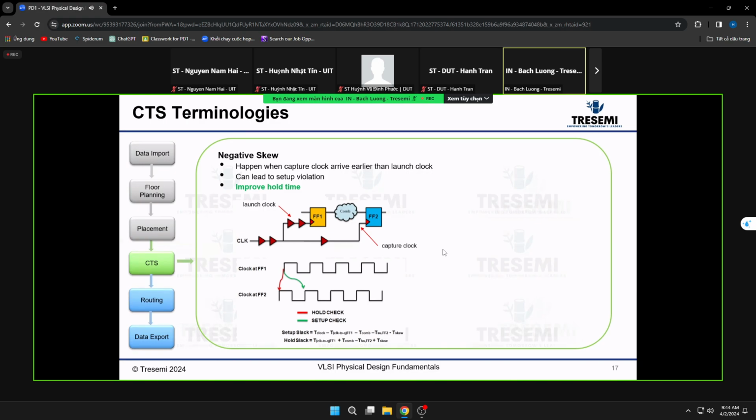That's right. So there'll be a CPPR adjustment. The tool will calculate that based upon the library and technology on the path. It will know the value per path per technology, based on the number of levels of logic that are common. Those values can change based on the number of logic levels and technology. So yes, those will be removed from the clock path.